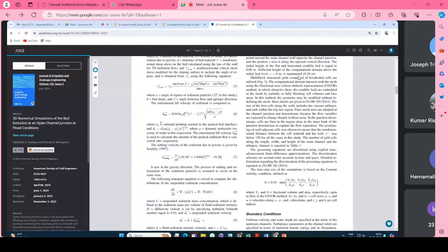So here you see the formula of the lift velocity. That's the velocity that comes from the bed particle to the flow, and these are entirely empirical equations, but of course in the framework of some theoretical knowledge also. And similarly, you see here how much the suspended sediment will settle on the bed by using this formula of the settling velocity. So we are now able to model the settlement, the entrainment, the suspended concentration, and the bed load transport. We could model these parameters using the numerical model.